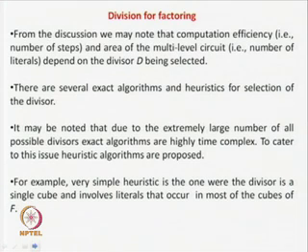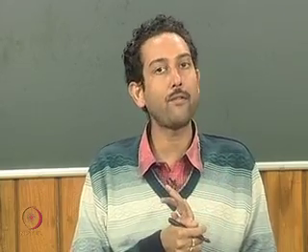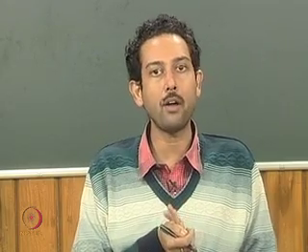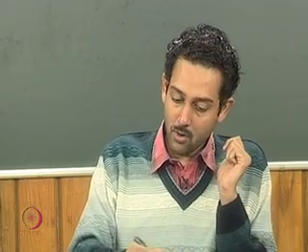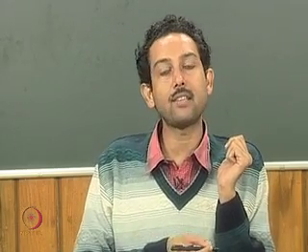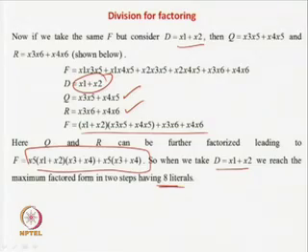Again, I am not going into elaborate detail, but just think of this. If you are given some 10 prime implicants, you have to find a subset of them, so 2 to the power of the number of prime implicants is the solution space. But in this case, depending on different types of factors, you can see the different types of representations that are coming up. So you can generalize and think how big the solution space will be. The solution space in multi-level implementation is much larger than in 2-level implementation.